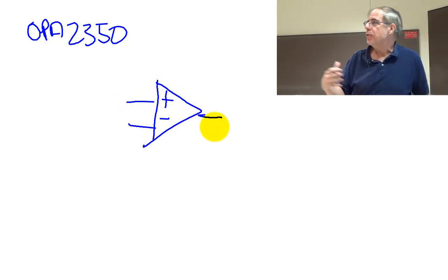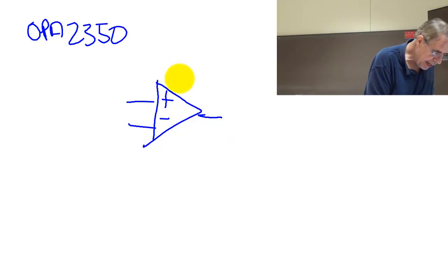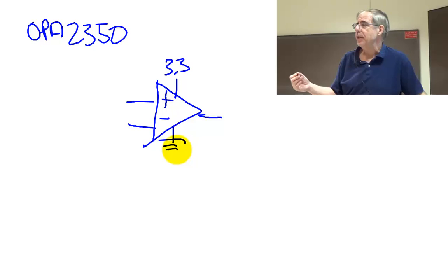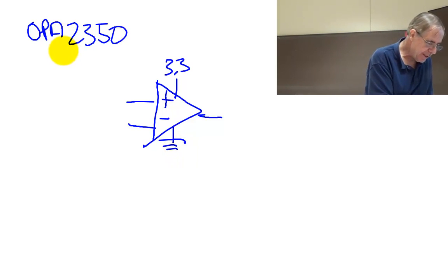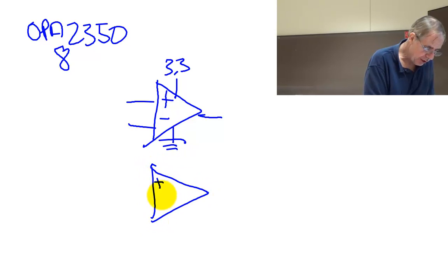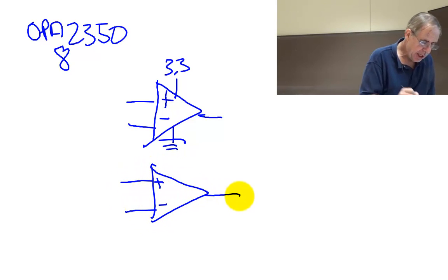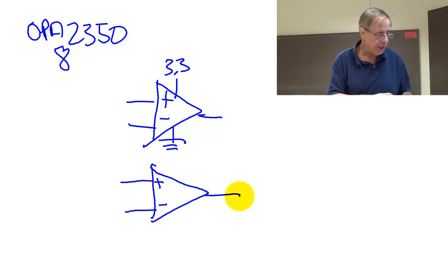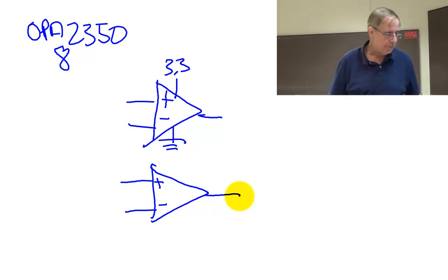you might have seen it with 3 pins. If you add the power pins and the other power pin, which we're going to connect to ground, there you got 5 pins. And this is actually an 8-pin. This is an 8-pin dip, and so it's going to be what's called a dual op amp. So those are the 8 pins that we're going to see here in Lab 9. So when you get the package, it'll actually have 2 op amps on it.